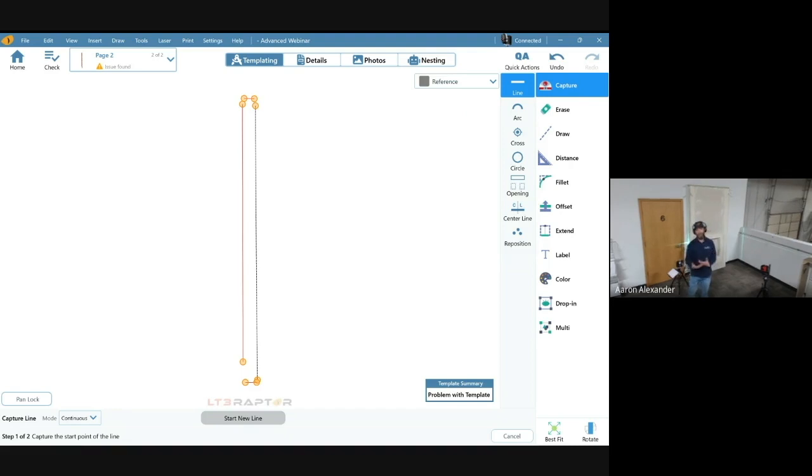Now, there's a couple options I have here with this style laser, okay? One option is this thing is projecting level and plumb onto my wall over here. Now, as you guys know, that's pretty far away from the plane that we have established right here. And that would definitely be breaking my rule of no more than 6 inches away that I'm going to take points. I would definitely break that rule. We're feet away. And we're going to shoot our points on that wall and pull them over here, okay?